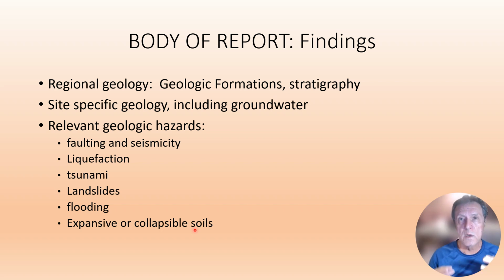Those wind-blown sediments are called loess, L-O-E-S-S. It's not a common soil everywhere, but it can be found in certain places, and it can be prone or vulnerable to collapse upon introduction of water from development, from irrigation, from water mains, etc. So that's another issue.